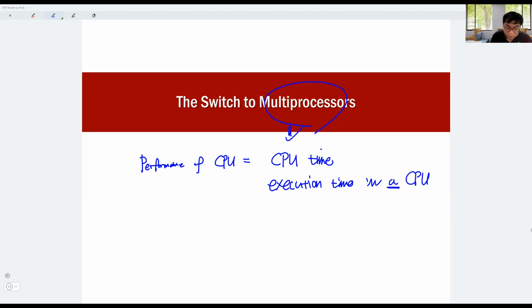So the problem is that if we reduce this channel length, actually when this gate is turned off, then this channel should be also turned off. This is the off state of the CMOS transistor. But because this distance is so narrow, even though this transistor is turned off, current flows from VDD to ground.